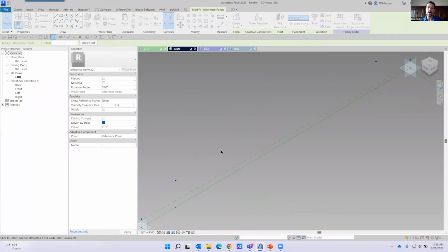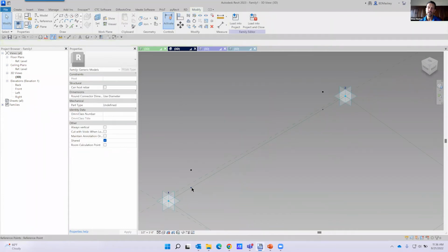And I've now got an offset value, right? So I'm using this point on this line to move in and out, then I'm going to use this point and this point up here to move up. So you can start really getting overly complicated as you do this, but this is how I have found, when we get into this, how you get through and set all of those up and start really making your panel as stable as it can be for adaptive components.